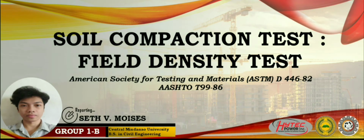Hello everyone, I'm Seth V. Moises and I'll be discussing two of the methods of soil compaction test. Soil compaction is necessary to increase the bearing capacity and stiffness of in situ or chemically modified soils. The first is the field density test, ASTM D1556 and AASHTO T191.